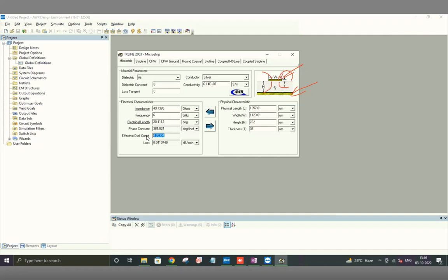That does a very specific microwave structure job, which we'll study later. This is the most commonly used transmission line, the microstrip, even though it does not support a true TEM wave. It supports a quasi-TEM wave, but it doesn't make a huge difference, since the main effect is a frequency dispersion, but it's small enough that it doesn't matter.